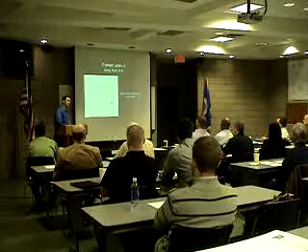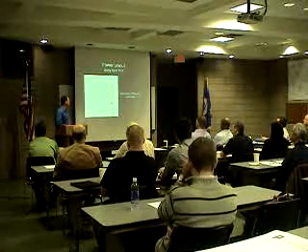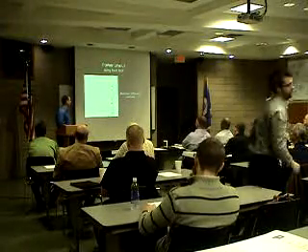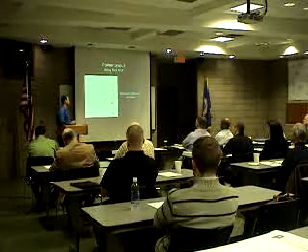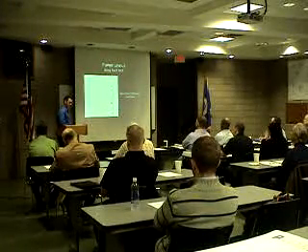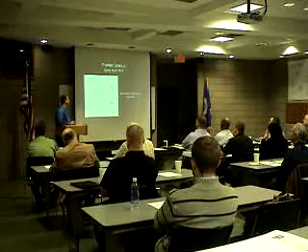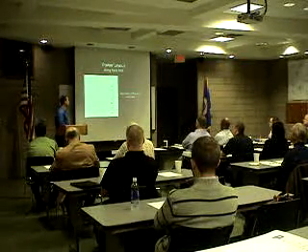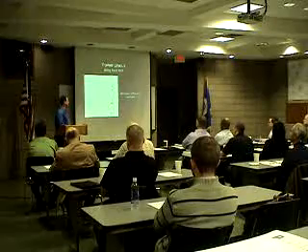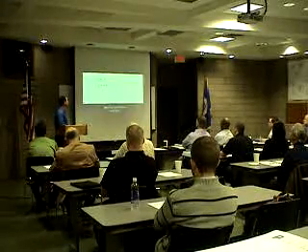So now we're going to talk a little bit about the power layout. As you can see here, this is our main open office area, and these right here are cubes along the wall. And so when we were putting the power in these, we basically just had to plan for one receptacle in each office for general use, and then a quadruplex receptacle for data.